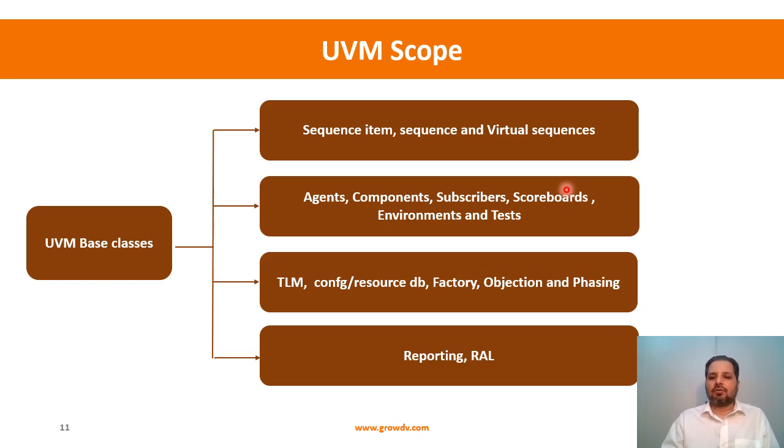And then in the end we have the tests. So the basic idea is the environment will instance all these guys. It will instance agents, components, subscribers, scoreboards, and then tests will instance environments, configure them, and run some series of sequences on the agents present within the environment. That's the basic idea.